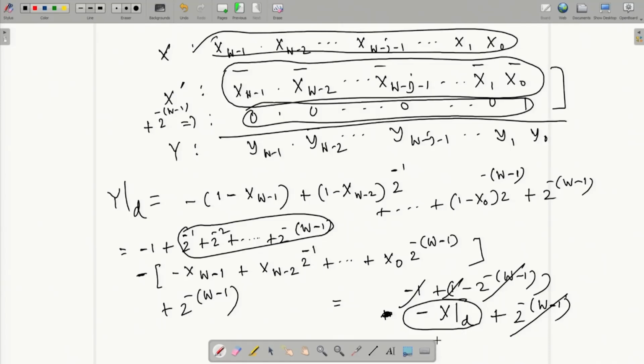This is the advantage of the 2's complement number system, that is, if you want to take a negation, if you want to do subtraction, you do not need to design a subtractor. You take the complement of each bit and add a 1 at the LSB, and the resulting word will have a decimal value equal to minus of the original decimal value. So, you just simply add whatever numbers, and that will amount to subtraction. These are the main advantages of the 2's complement number system.